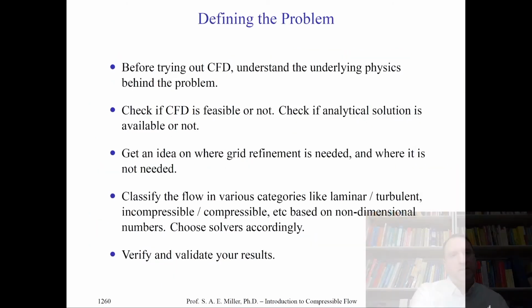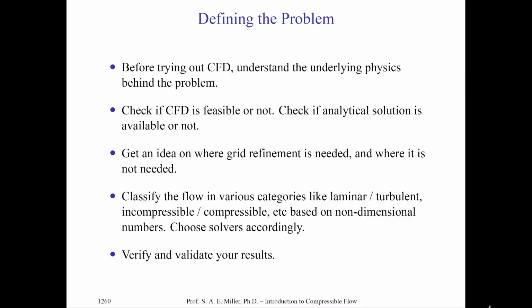The first step of CFD, of course, is to define the problem. I believe this is the hardest part of engineering: to understand and define the problem. Before we try out computational fluid dynamics, you must understand the underlying physics behind the problem. You should always check if CFD is feasible or not. You should also check if an analytical solution exists for your particular problem. If you have an analytical solution, there's not much reason to do CFD.